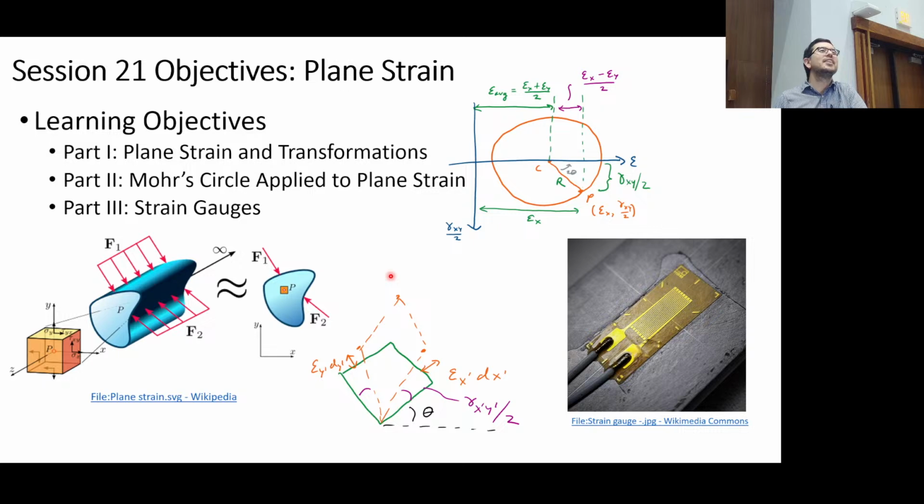It was just like, as the load was pushed down, it stretched the strain gauge, which caused a change in resistance. Okay, but the strain gauge was on what? It was on the load cell. Okay, so what was the structure? Oh, so it was a beam. Yes, see, that's a critical piece of information we're getting. Were you loading it like a beam, or were you loading it in tension? How were you loading this bar?